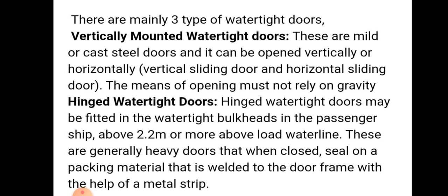Vertically mounted watertight doors means these are made of mild or cast steel, and they can be opened vertically or horizontally: vertically sliding door and horizontally sliding door. This means of opening must only rely on gravity.